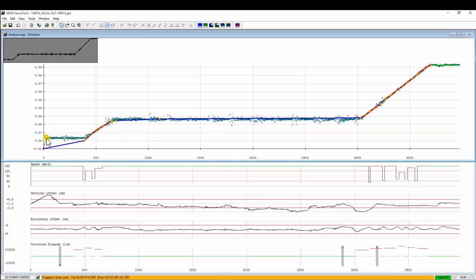So we have the first calculation, and you see there are many split points, which means that the element radius is changing and it's creating new and new split points. So this is definitely too much. We will not get into any good solution. I would recommend you delete redundant split points, so each element has one at the beginning and one at the end.